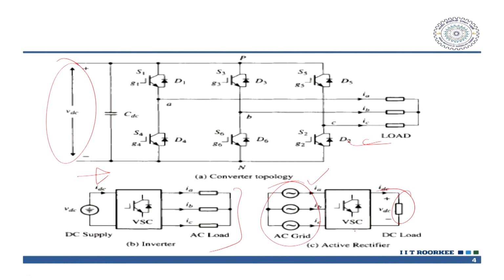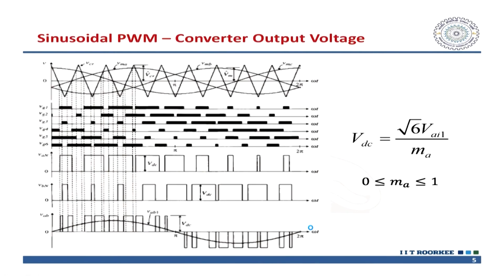Then it becomes an active rectifier, and you will be charging at unity power factor. And there also you require to control the P and Q. So, it has a different mode. Once you are sending power DC to AC, then P becomes positive. If it comes from the grid, it becomes a load, and P becomes negative.